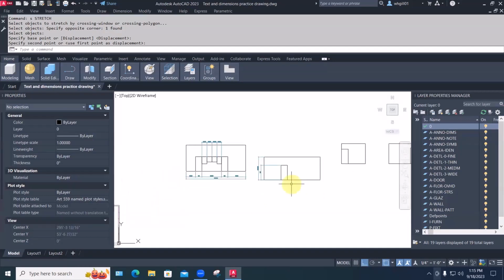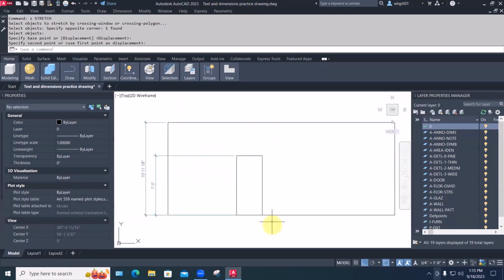A couple of things about dimensioning doors. That door over there, how many of you, 20? There are about 15 different sizes for doors in your elevations. The closet door. The deal with doors is basically all these standard doors are either 6'8" or 7 feet tall and an even number of inches wide. The frames are made, let's say, a 36-inch opening, and the door comes in at 35 7/8 or something, but they're all treated and drawn as 32, 34, 36.